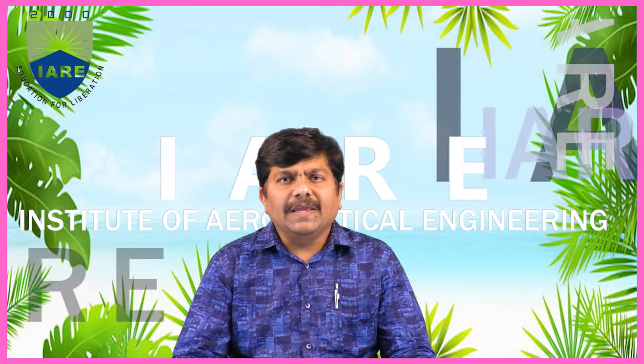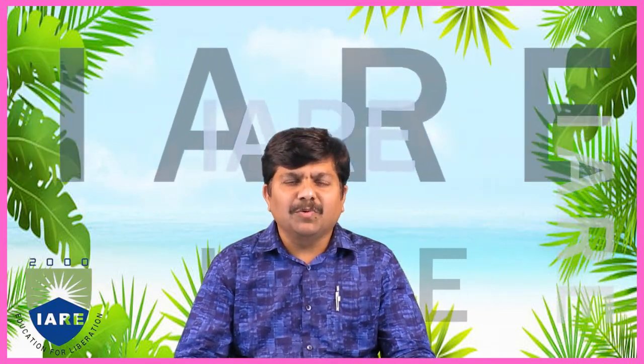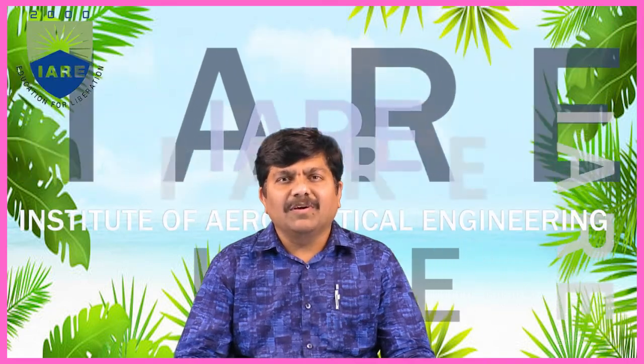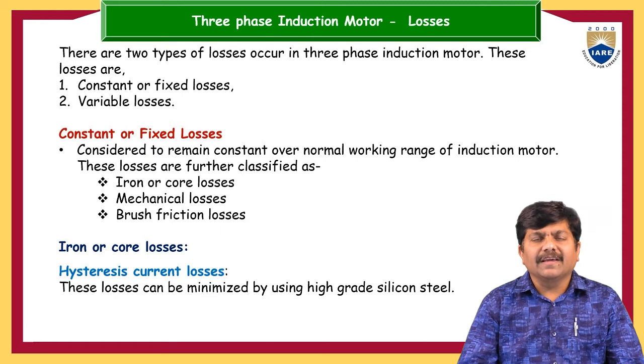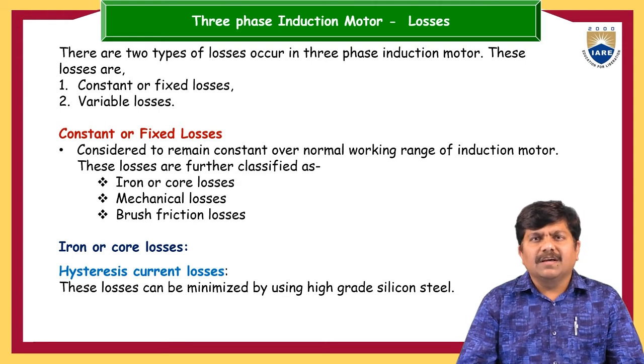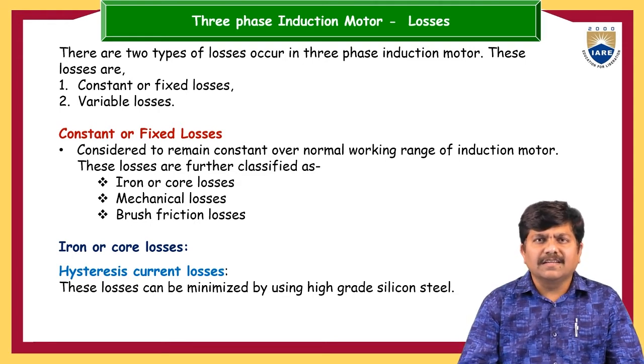So broadly, the losses that occur in three-phase induction motors can be classified into two broad areas. As we know, some of the components are fixed and some of them are variable. So based on this, the losses could be classified into two categories: variable losses and constant losses. Now first, if you are talking about the constant or fixed losses, again these can be classified into more categories. Those are iron or core losses, and mechanical losses.